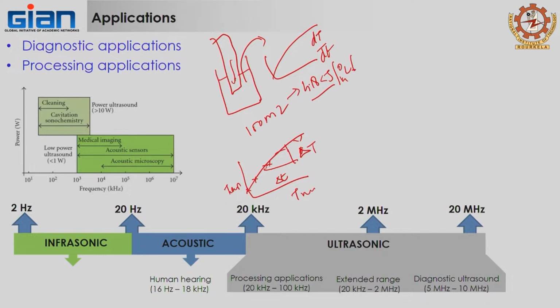So the calculation of power becomes, what is the equation of power? P = m Cp delta T by delta t. The slope you get from here, specific heat is here, mass is 100. So you get your power. This is the calorimetric method for measuring the power of an ultrasonic system.